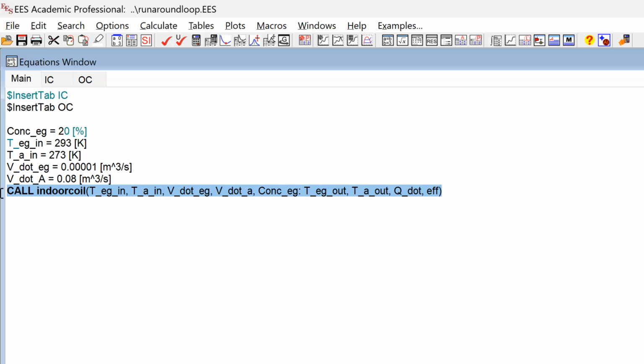So what we'll do in the next video is actually integrate these two coil models with the fan models and the pump model, which turns out to be not trivial, right? Because you have to be at the right place on the head flow curve for all the fans and the pumps relative to the system, which in this case is these coils.